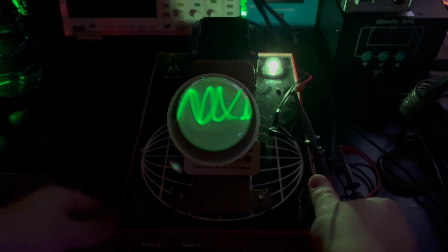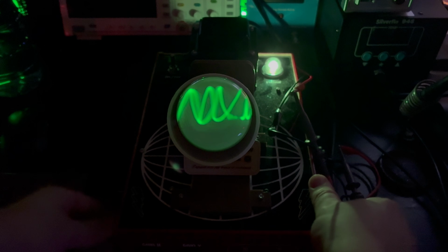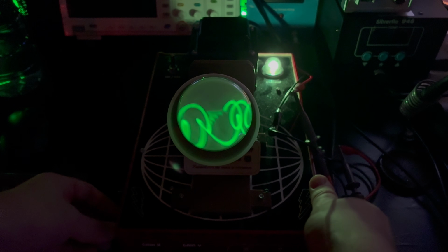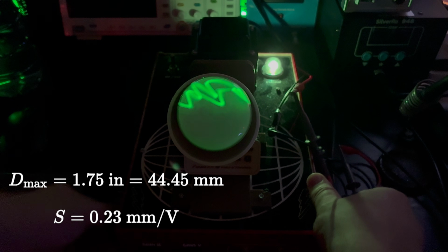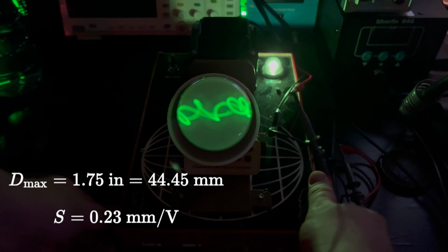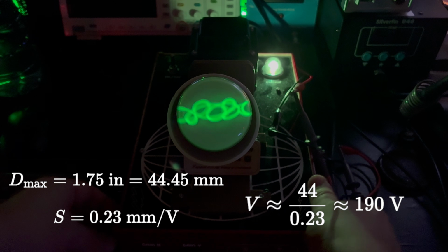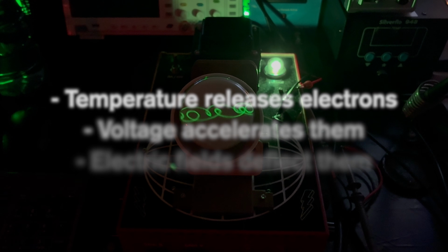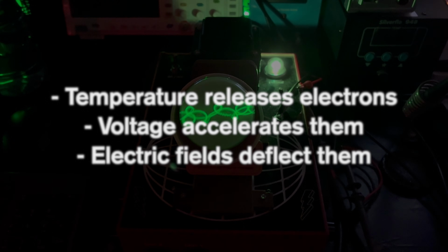An important consequence of the physics is that the sensitivity is inversely proportional to accelerating voltage. Because this tube is running at about 710 volts instead of the nominal 1000 volts, the electrons are moving slightly slower. Therefore, the beam is easier to deflect. To move the beam across the full screen, about 44 millimeters, requires on the order of a couple hundred volts across the plates. This is why the deflection amplifiers must operate at a relatively high voltage. So the entire system reduces to a few relationships: temperature releases electrons, voltage accelerates them, electric fields deflect them, and the result is motion made visible on the screen.